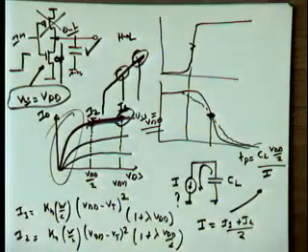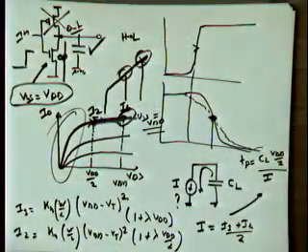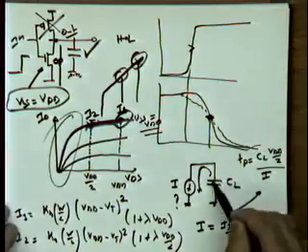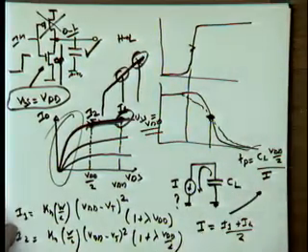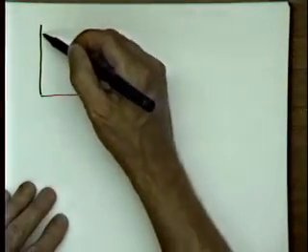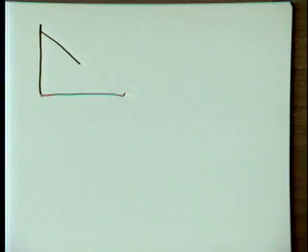Yes? This one here? Oh, this one here? So let's look at it: you have a capacitor, which you discharge with a constant current. Okay? That's what we're doing. It's a constant current. You know that if you do so, the voltage is going to look like this. You start at VDD, and you will get a linear reduction of the voltage. Right? If I have a constant current discharging a capacitor, that's what I'm going to get.